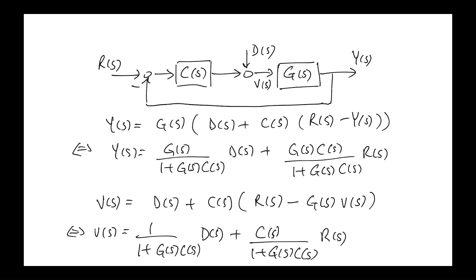I think it's useful to think of the model of the plant as including such things as disturbance signals, and I've absorbed the output disturbance around through to the reference here. It enters the loop in more or less the same way, and similarly for the sensor noise. We're interested in understanding when the closed loop will be stable in the sense that bounded signals at the inputs to the closed loop system result in bounded internal signals.